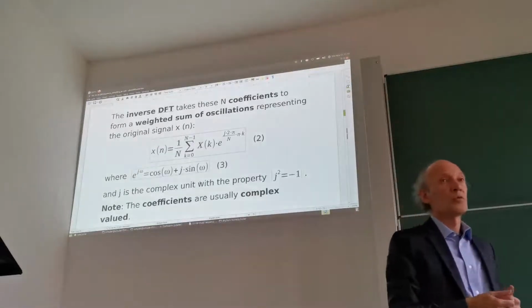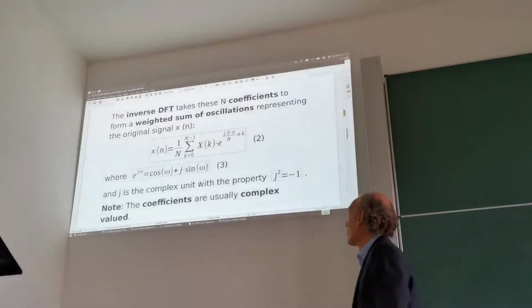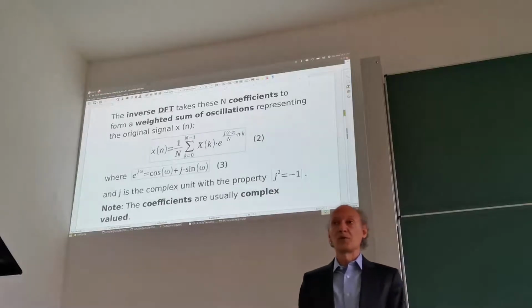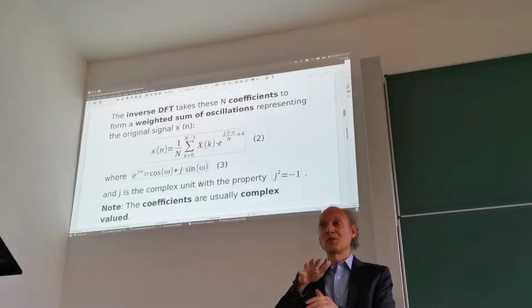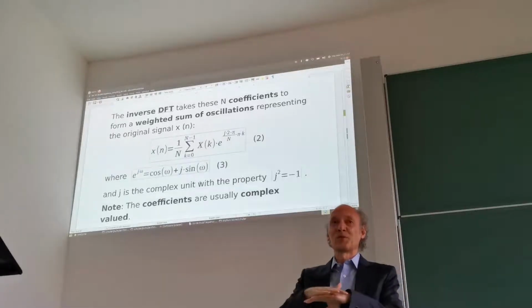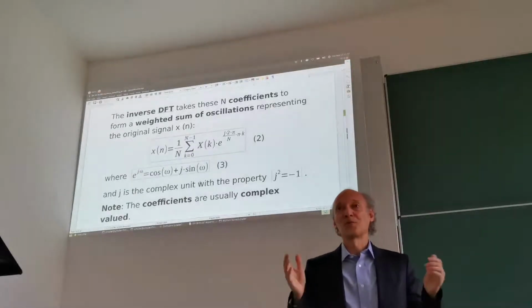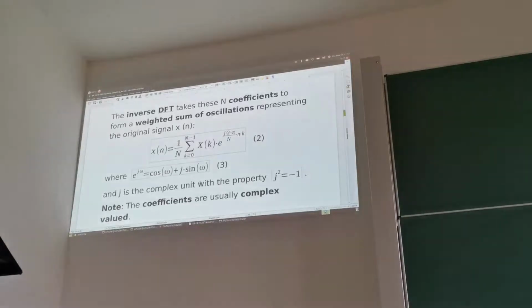So this can now be used to analyze our image, because then we can take a look at those xk for the high frequencies. If we have high values for high frequencies, that means we have a problem with aliasing. If we have very low or disappearing values xk for high frequencies, that means we have no problem doing the sampling, because only at high frequencies will we have a problem.